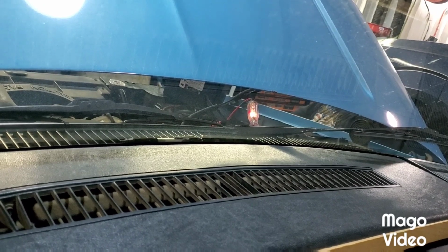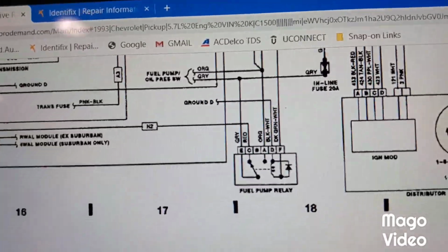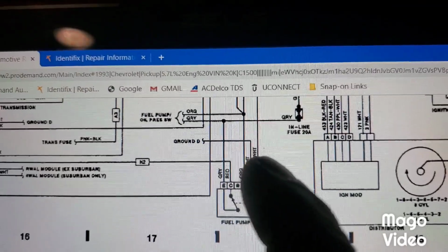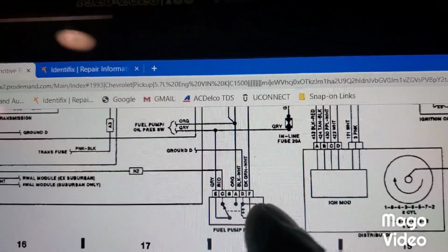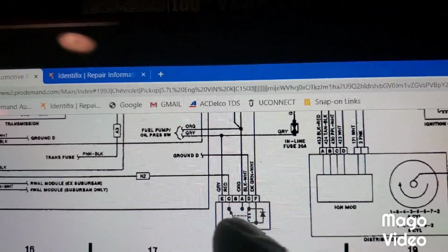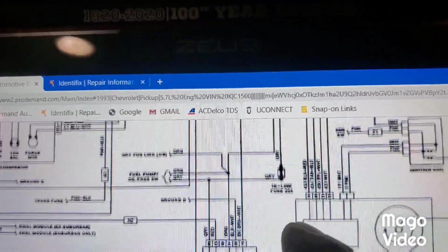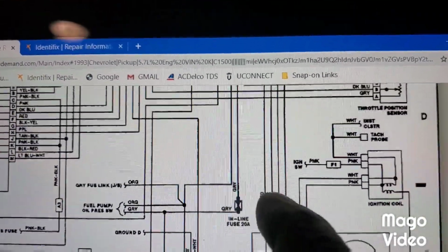Crank it. And 12 volts stays there, okay? That's a full-time power. So let's think about this. If that's a full-time power coming from the orange, and this switch closes, it means you're going to have power coming up through the oil pressure switch, out this way on the inline fuse, the 20 amp fuse, right?